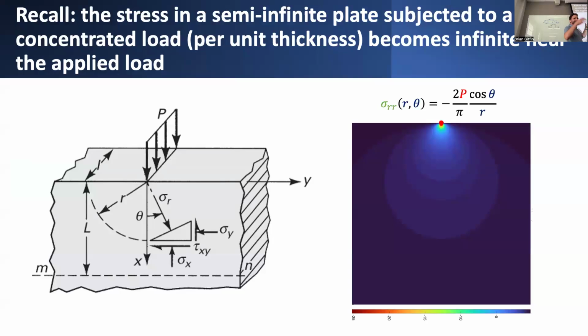Again, if we're talking about an infinite plate, the plate technically has a finite width, and this concentrated load is distributed over this finite width. Even so, we get a practically infinite distribution of stress, and it depends again on this 1/r thing. You probably could figure out a reasonable way to estimate the max stress as you continue to go down. But this would give you a reasonable way to do that.